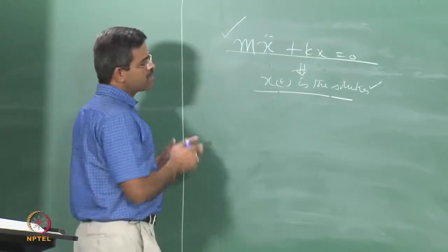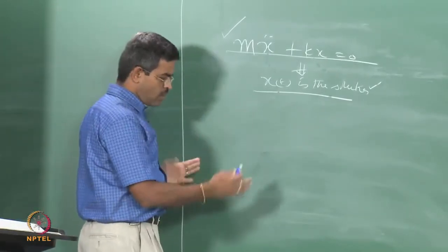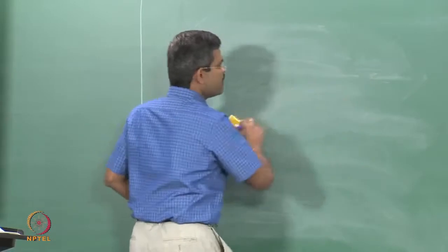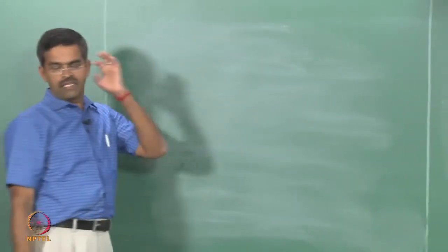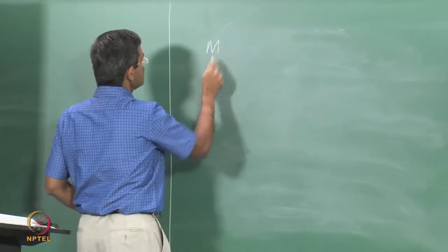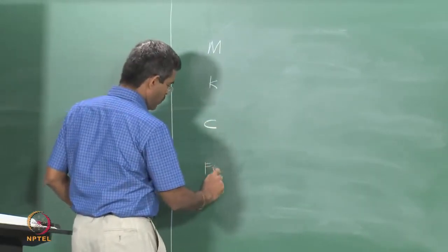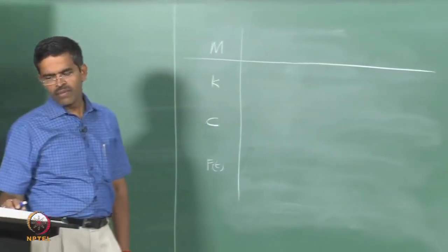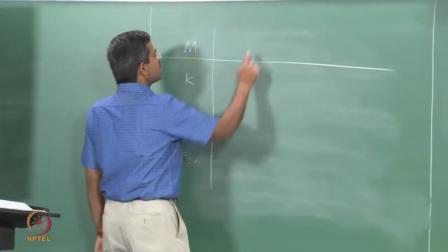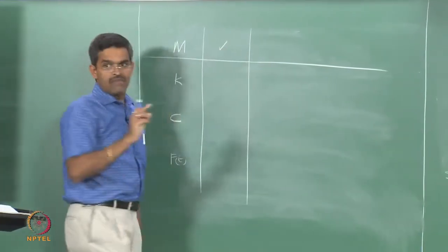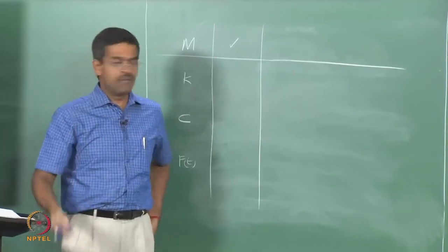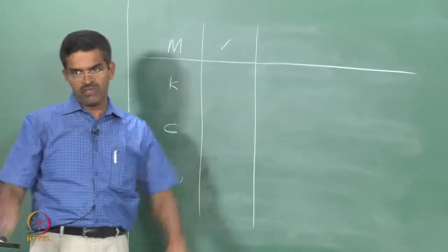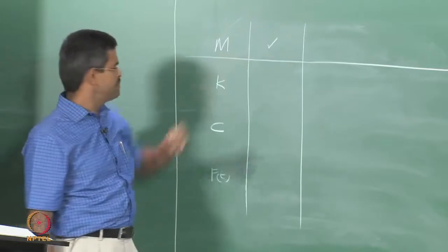Okay. Now, let us get back to what are the essential characteristics of single degree freedom system model. Same question asked back again, which started this class actually. The essential characteristics are mass, stiffness, damping and force. These are the essential characteristics. Okay. Now, let us see, mass has to be present in any given system, otherwise there is no dynamic analysis, because we already said dynamic analysis is possible only when it has got a representative inertia force present and mass proportional. So, mass need to be present in a given system.